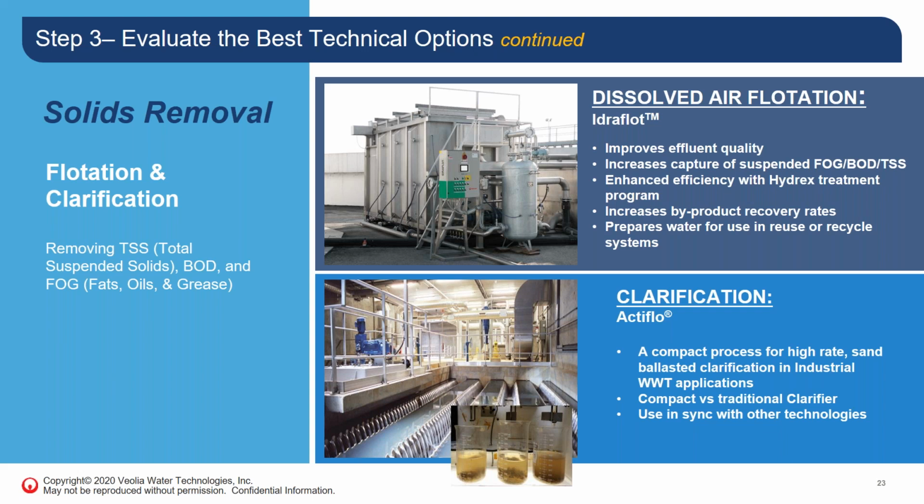On the top of the slide, much like the digestion technologies mentioned on the previous slide, dissolved air flotation can be used where you've got high BOD, COD, and TSS. The Veolia Hydroflot technology is excellent because it does have a modular design and a patented air injection system that enhances the float that you get, the removal of these suspended solids with, again, a smaller footprint than traditional technology.